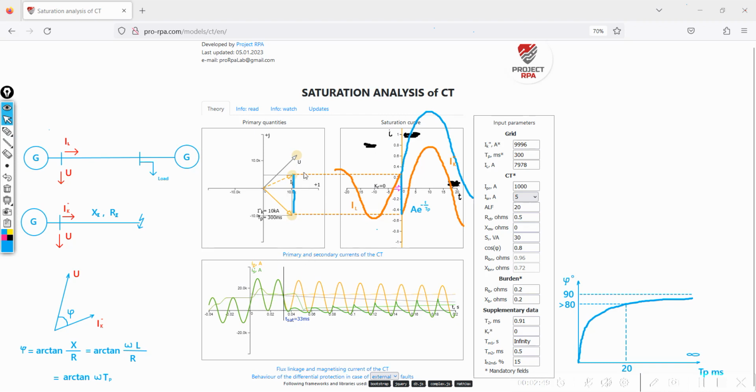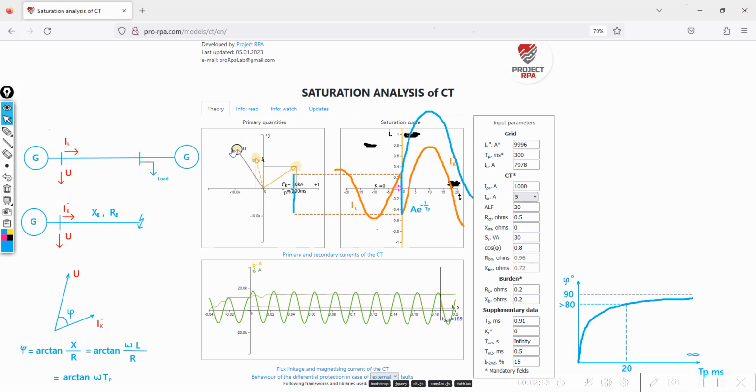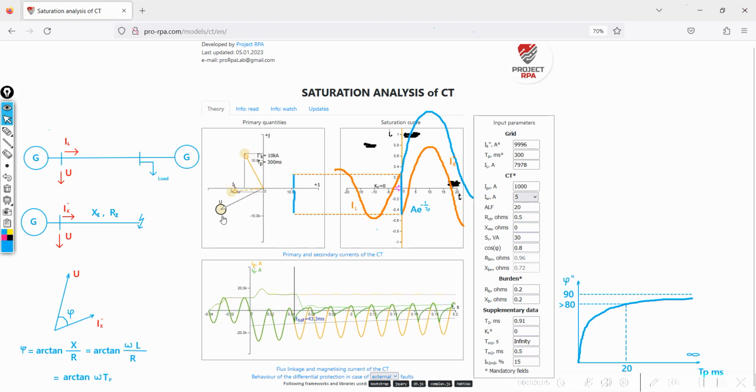If you increase the fault inception angle so that this time the two upper lines coincide, then the initial value of the DC component becomes 0, which can be seen below. The narrow line disappears and the current curve is not shifted. If the fault inception angle is turned to the third quadrant, then a maximum displacement can also be set there.